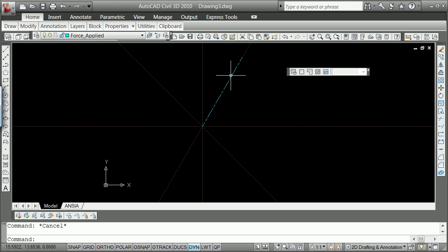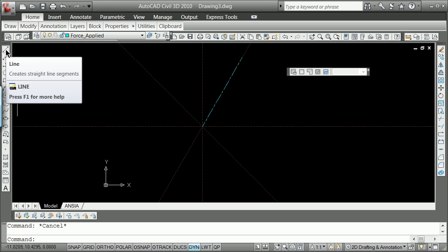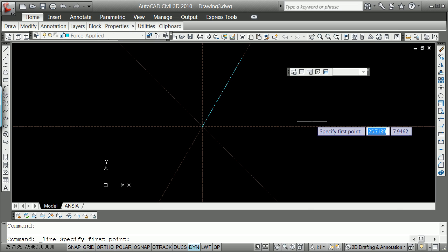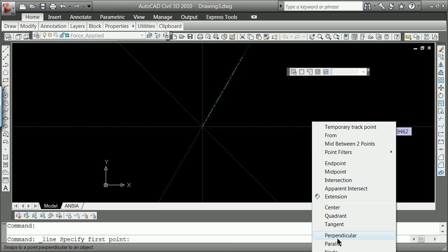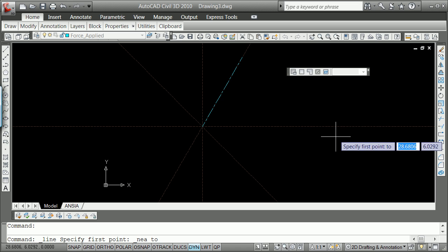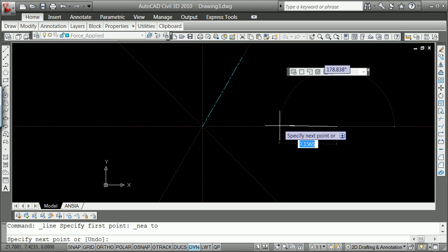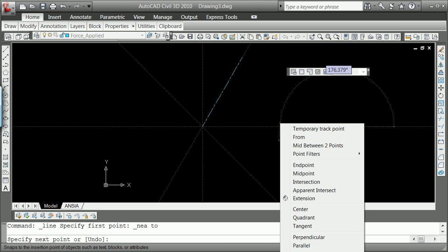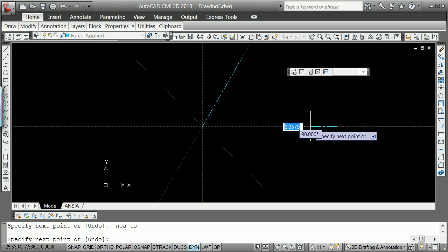We'll look at how to change line types in a little bit here. So the arrow is kind of shown in the force in the line type. We've got this one here. If you want to really start the way it's drawn, you might go line, shift right click, near in this case. Take it in this direction, shift right click, near. Whatever you want to do here, and then you can left click with the dynamic on, left click. That is supposed to be 12.